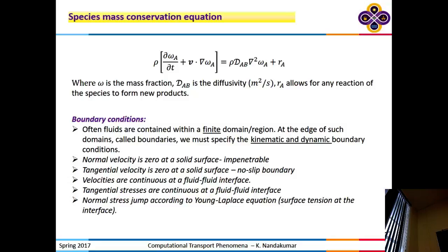I can integrate that and know what the flow rate is. And I can put two pressure gauges here and find what P1 and P2 are. So I can develop a relationship between delta P and velocity, assuming this model and the no slip condition.